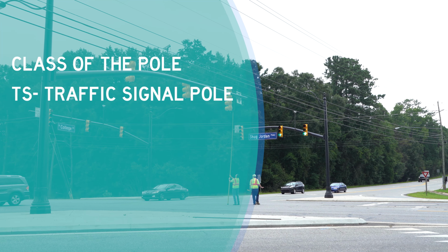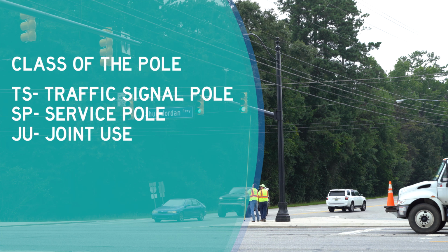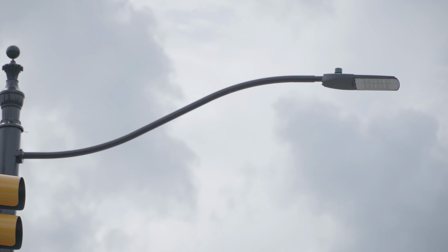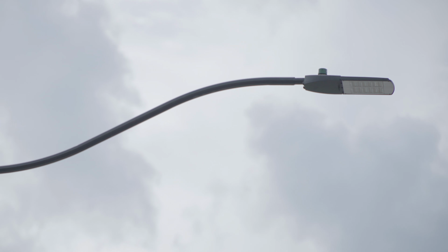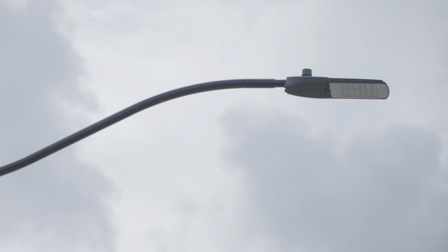TS is traffic signal pole, SP is service pole, or JU is joint use. Next, we need to count the number of luminaires attached to the pole and a description of the condition of the pole. Lastly, we can upload any documents or images from the location.